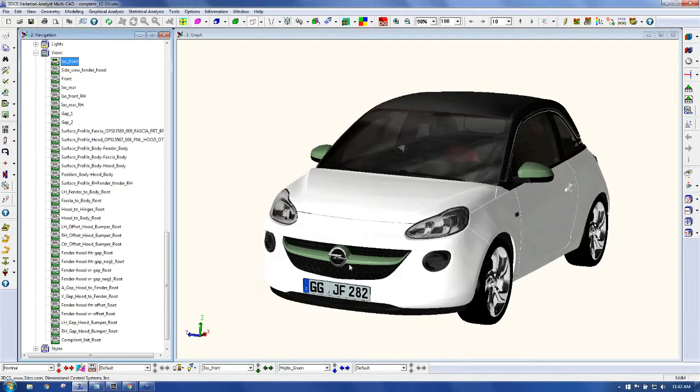The one thing that I will make sure to tell you is no matter what visualization tool you're going into, to make sure that your scale is correct, that the scale that your model is in 3DCS is the same scale that your model is in visualization, because that's going to affect shadows, it's going to affect ambient occlusion. If your model is scaled up, let's say 1,000 times, it's going to look different. Whether it visually looks different on your screen or not, the actual interaction would be different.